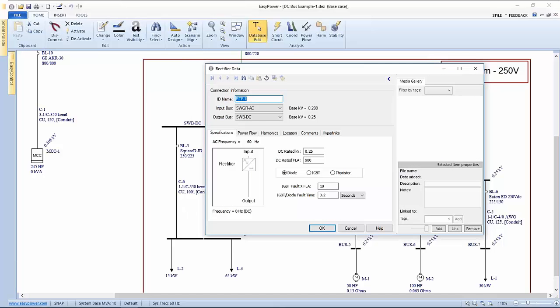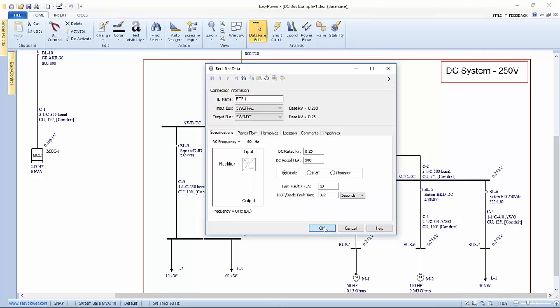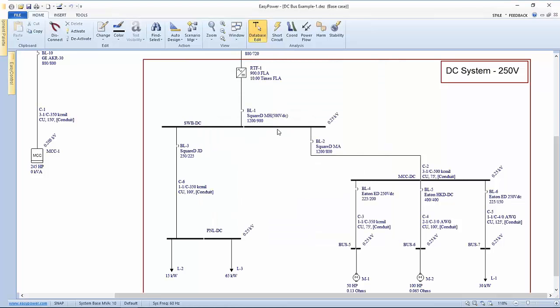The maximum fault current and the fault time are numbers that will come off the manufacturer's data sheet. For the most part, the diode or IGBT model is explained in the data sheet. The diode model is the simplest, and we follow that IV plot that we showed earlier. But for thyristors and IGBTs in a power flow model, there's some compromises made just because the equations themselves are fairly complex. So at that point, we have the ability to have contribution from rectifiers.